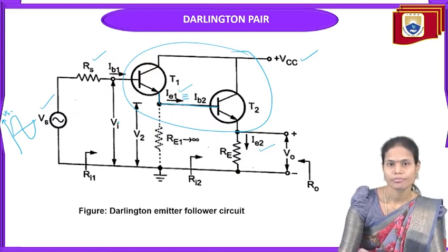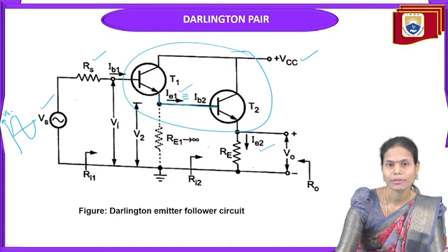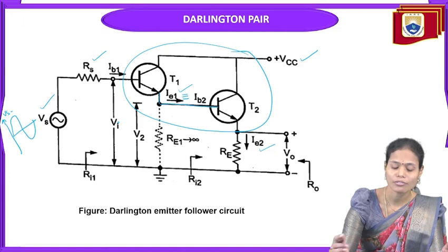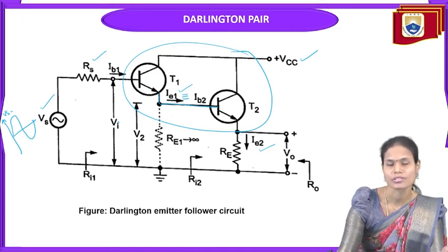In the case of single stage amplifier, to do the analysis, first of all we have to remove the supply voltages as well as any capacitors which are present in the circuit. We have to short that, and we have to replace the transistor with its hybrid equivalent circuit. But in the case of multi-stage amplifier, how many stages are there?